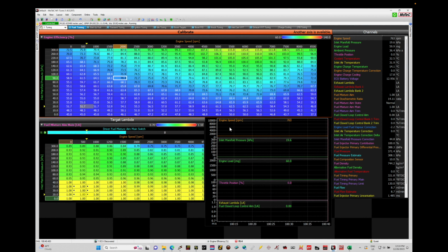Okay, so let's get started. We're going to be taking a look at setting up our ignition coil dwell in our Motec M1 systems. Now, ignition coil dwell is going to depend on the type of coil that you're running with your ignition system. So whether you have, let's just say, a Denso coil or an LS GM-based coil, they'll have different dwell times. We have to program them differently.